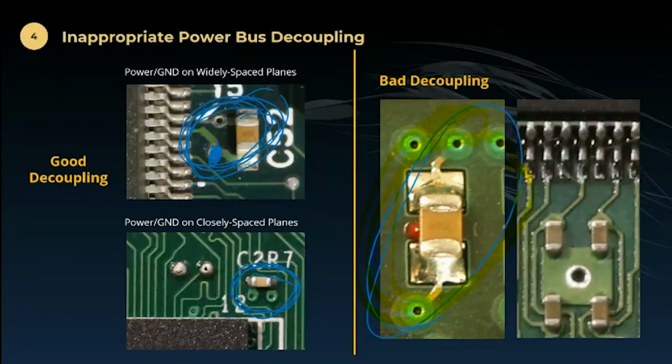Anyway, going off the ends of the pads is not good. We need to get the vias close together, and it's certainly really bad to share vias. Decoupling capacitors have to have their own connections to ground. We can't share connections to ground the way we're seeing there.